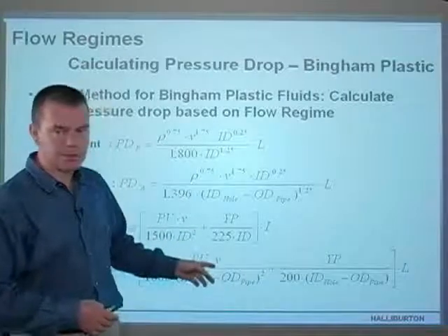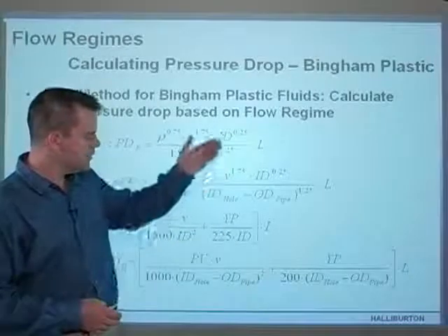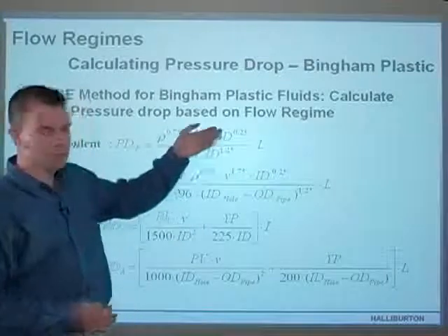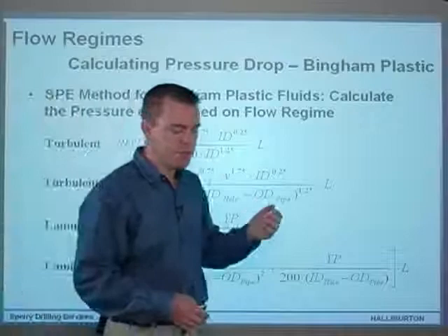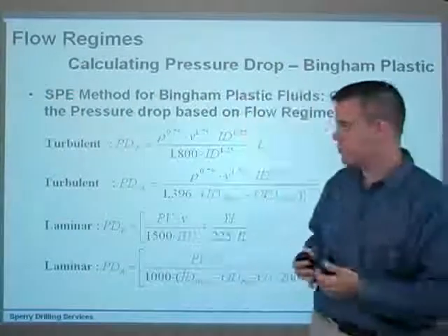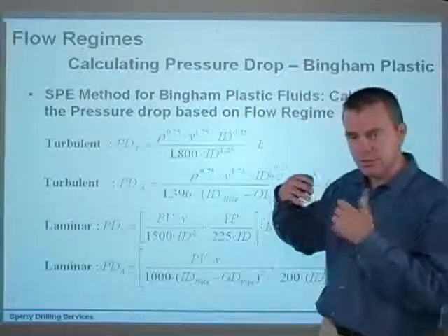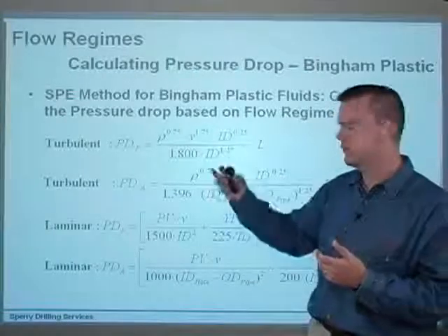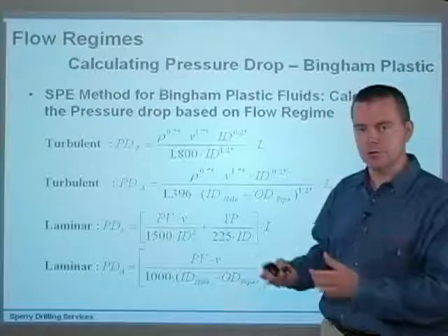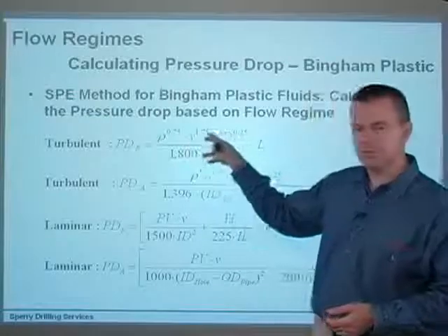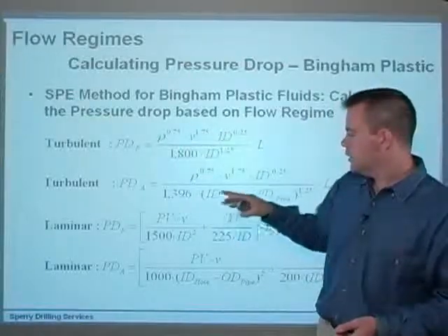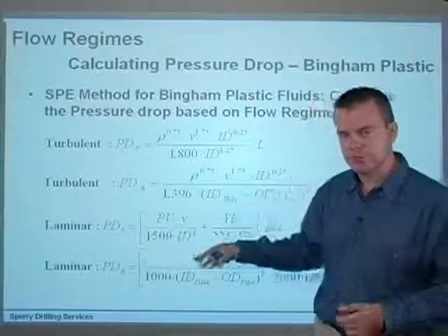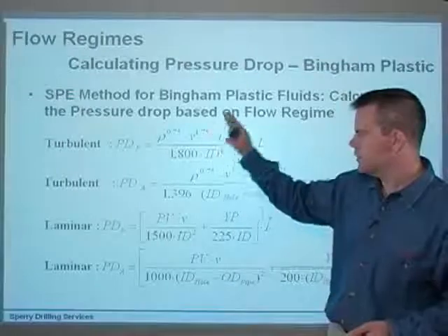Here it's just velocity. So as I was saying, if you double your flow rate, or double the annular velocity, or the fluid velocity in the pipe, you pretty much quadruple the pressure, because it's very nearly a velocity squared equation. Here, if you double the velocity, you're pretty much going to just double the pressure. That's the difference between these.